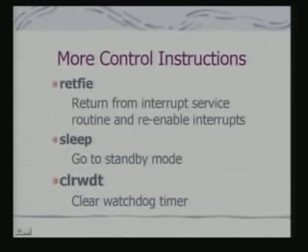Effectively nothing, because in both cases you need to get the return address from the stack. In case of PIC, you have got a hardware stack, so the return address will be stored in the hardware stack and you have to get the return address from that hardware stack. But in this case, this instruction typically re-enables the interrupts.